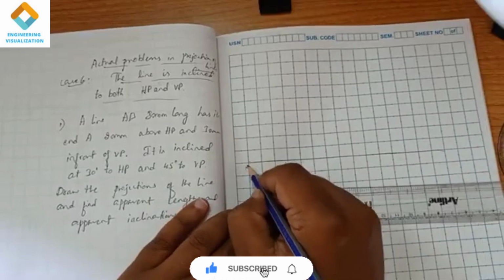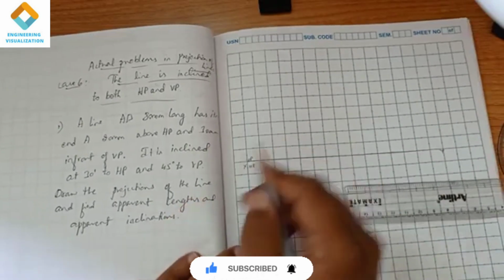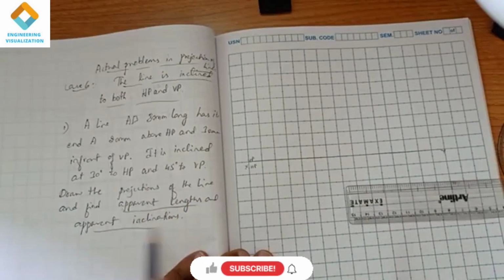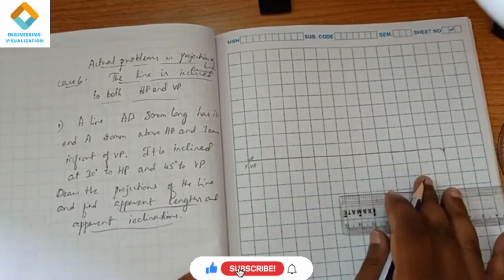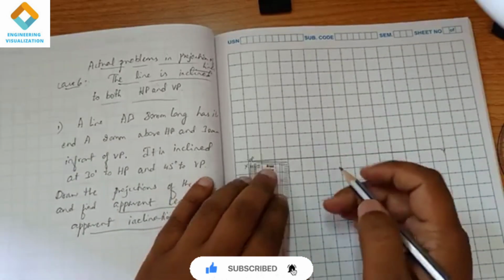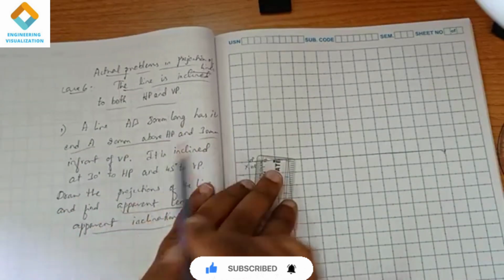So XY, VP, HP. In this problem we have to draw the projections of the line and find the apparent lengths and apparent inclinations. As we have discussed, apparent lengths are nothing but the reduced lengths, which we have to find out. First, the end A of the line is 20 mm above HP and 30 mm in front of VP.